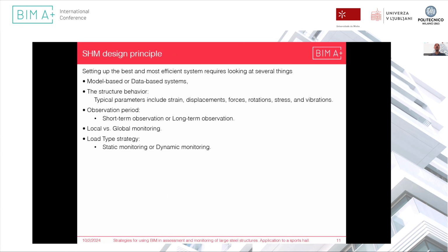The guideline to set up the structural health monitoring plan. We need to decide whether it is a model-based or database system. Should we develop a model by finite element or modal model, or only collect the data and compare it between the damaged part and undamaged part? What type of data do we need to monitor? We have strain data, displacement, force, rotation, and vibration.